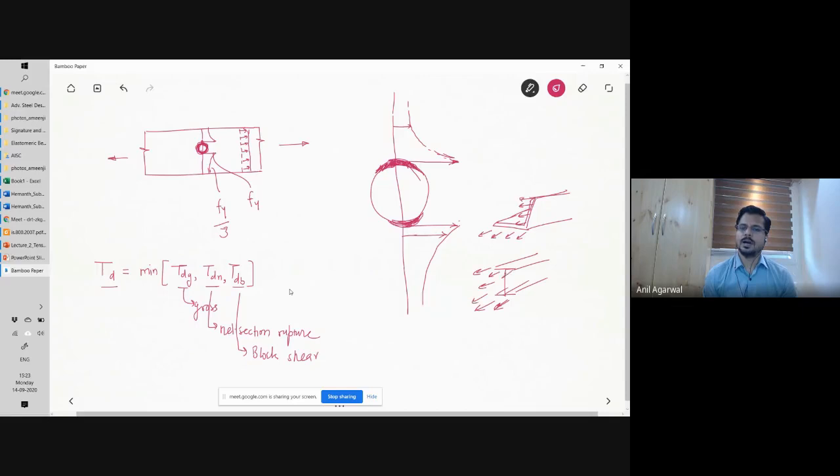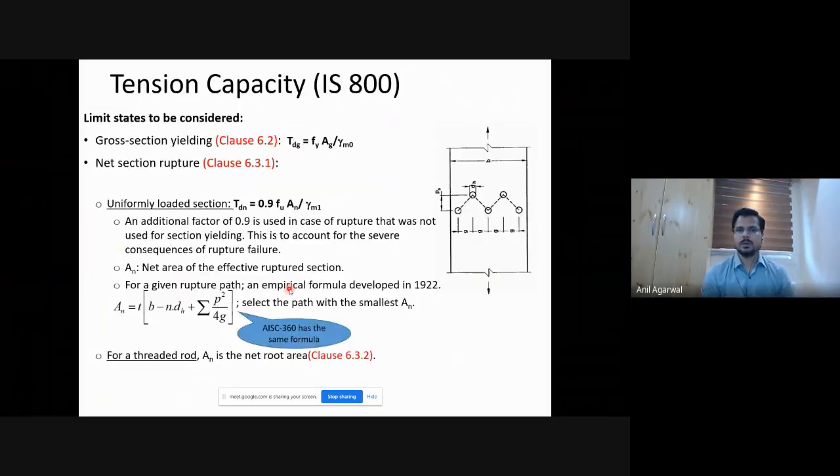It is very, very hard to make sure of such a thing for I sections, for angle sections, but it is much easier to do that for a plate or a rod, or even a pipe. Therefore, these equations are applicable only when the stresses are uniform. That is, the net force is acting at the centroid, and it is applied far away from the location of interest so that it has distributed uniformly.